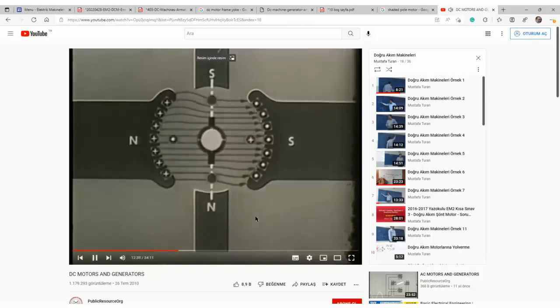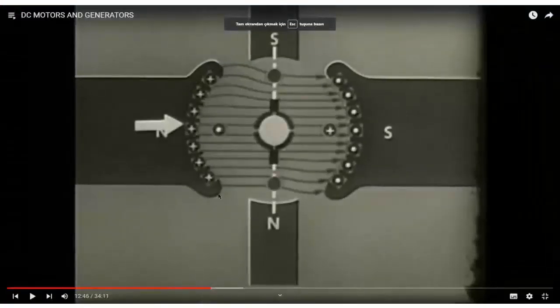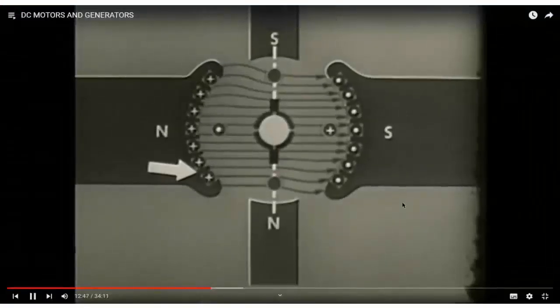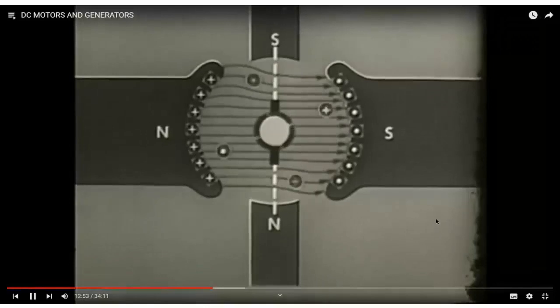In addition, to further counteract armature reaction, windings called compensating windings are sometimes placed in the main pole faces. The current in these windings is armature current flowing in opposite direction to the current in the armature conductor.